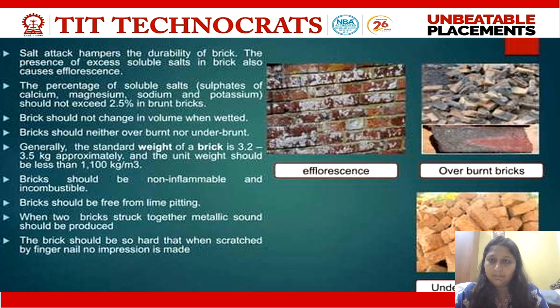The brick should neither be overburnt nor underburnt. Discussing manufacturing bricks, it basically consists of three main steps. The very first one is preparation of clay. Second is molding, which may also include drying. And the last one is burning.